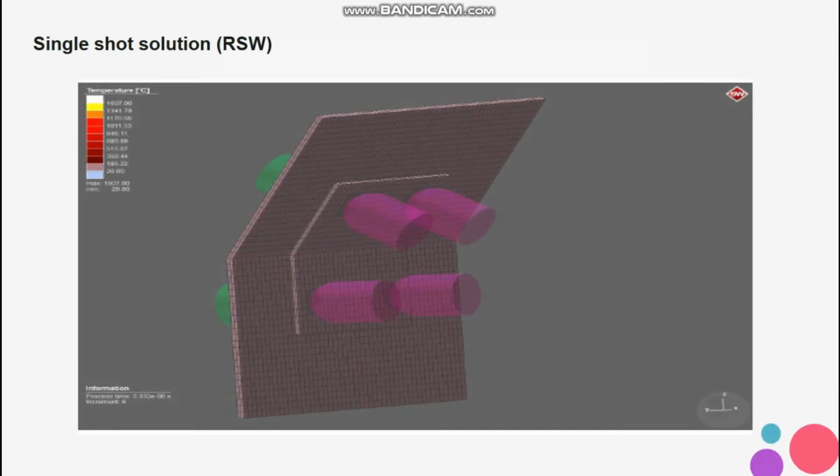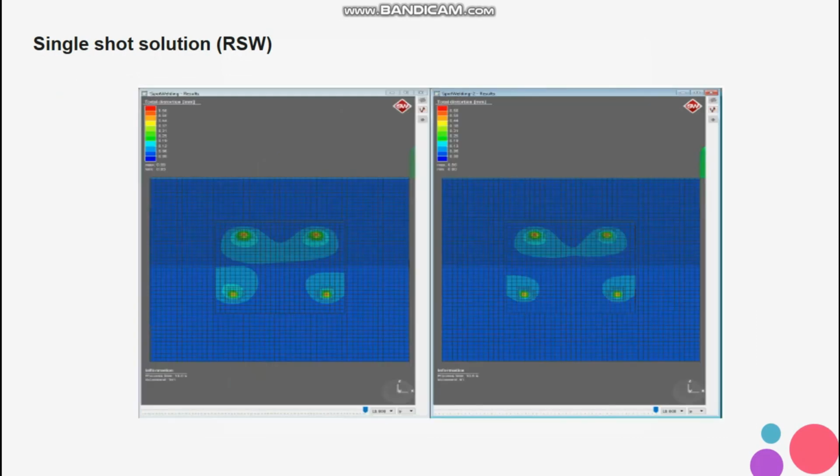When the single shot is active and the simulation is started, Simufact.welding will automatically pair every spot weld that is present. The result accuracy differs slightly in the below shown comparison, but this can change in other models. So please be careful when post-processing the result and be aware of decreasing result accuracy when using simplified approach.